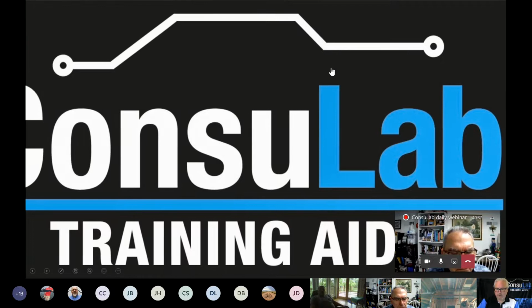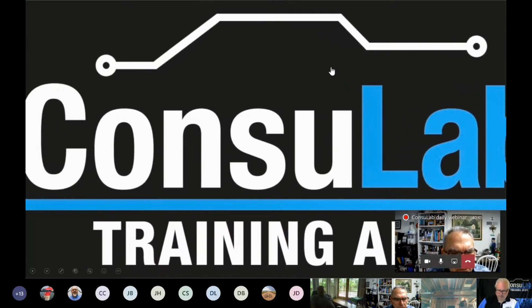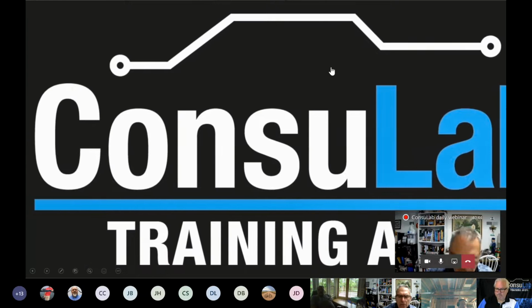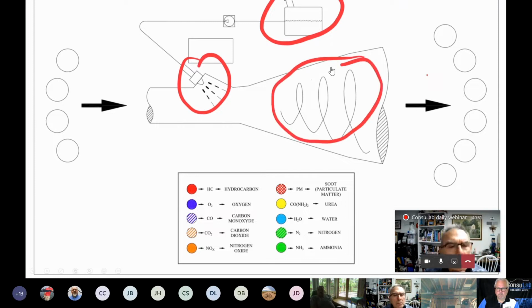Assignment 5. This is the 5th of the series of assignments. You may have to bounce your volume up a little. Aftertreatment system. The diesel exhaust fluid, or DEF, injector, and spiral mixing chamber are located next in this system. In this assignment, the exhaust gases and other components that travel through the mixing chamber or decomposition tube need to be identified.